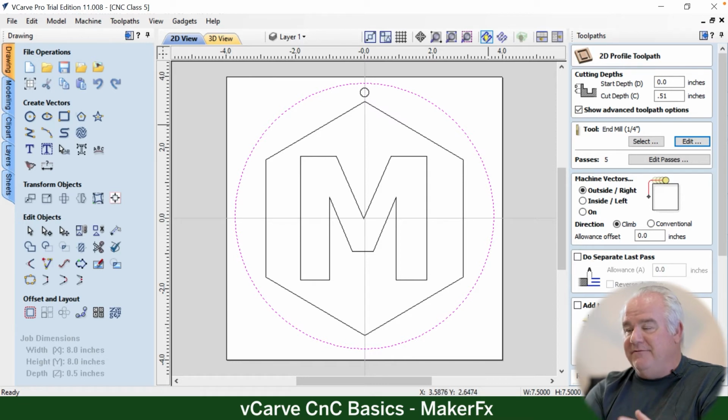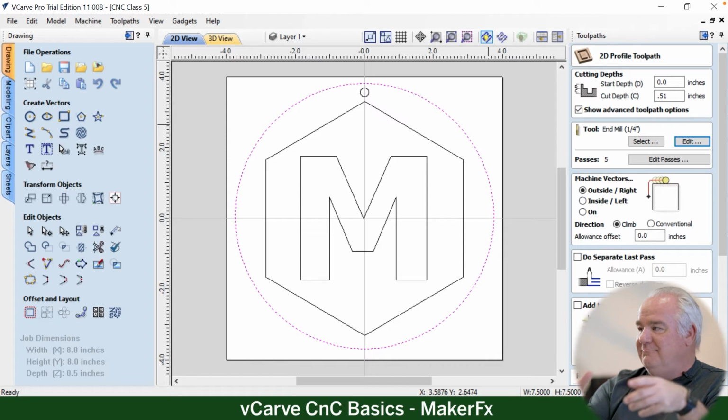There's kits on Amazon you can buy for different bits, the shapes and stuff, right? A lot of what's in those kits are V bits. You may also have a 1/4 inch end mill, an 1/8 inch end mill, and some different size V carving bits, whether 90 degree or 60 degree. I have a collection of bits that I brought with me today that we'll see when we get out in the shop. You'll see me put the bit in the machine, but I want you to also have the opportunity to use the tool and put that in the machine and understand how that works. Most of what's different with the V bits is that you get a different outcome with a 90 degree versus 60 or a 15.